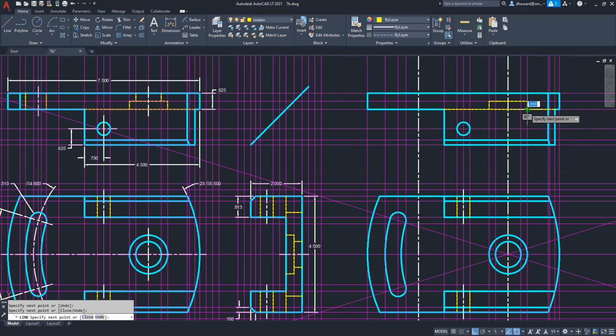So that right there is the counter bore that I just made. And then this is the hole continuing all the way through. And lastly, this arc. So the arc in the side view, it's kind of a weird thing. Basically, you got to just show the extremes. So that's the extreme edge on one side, and this is the extreme edge on the other side.